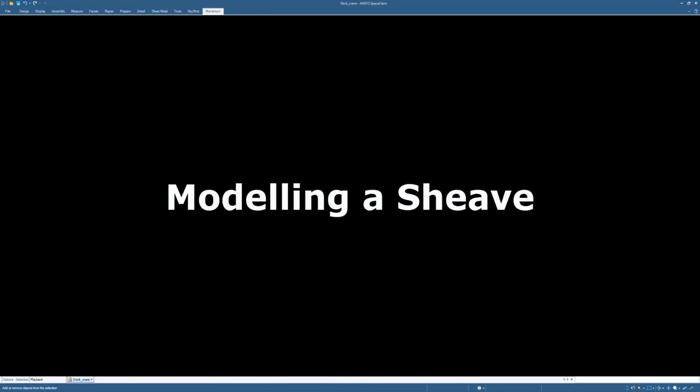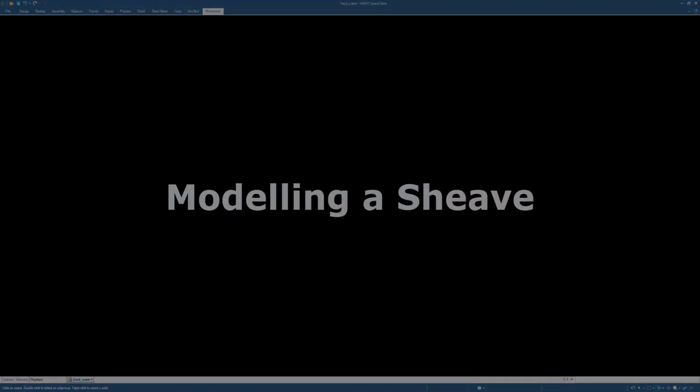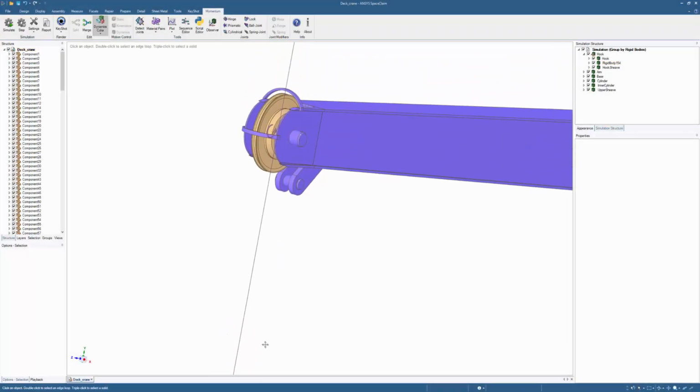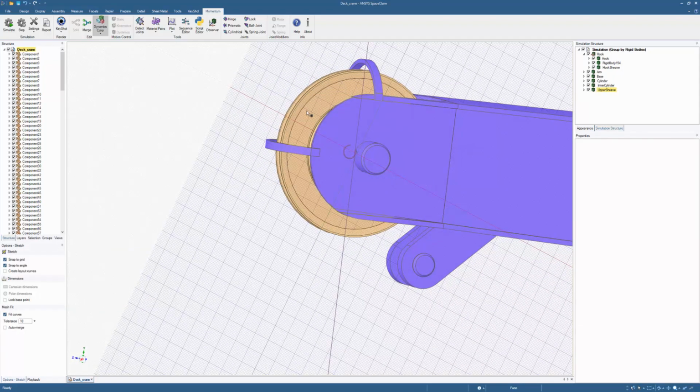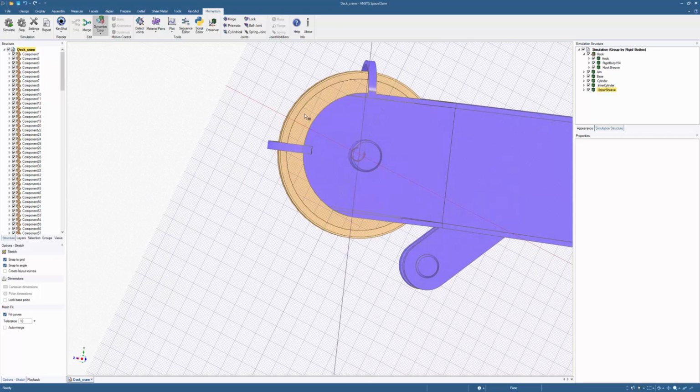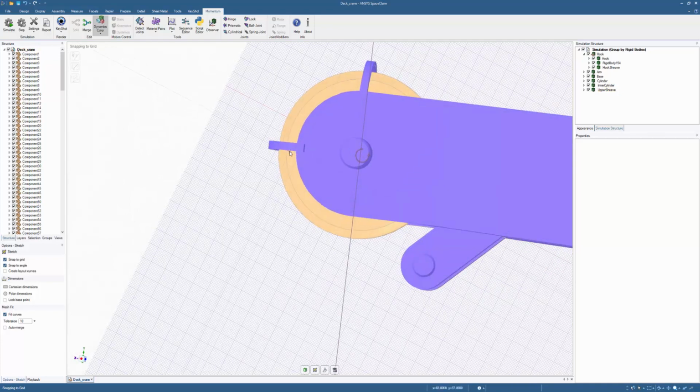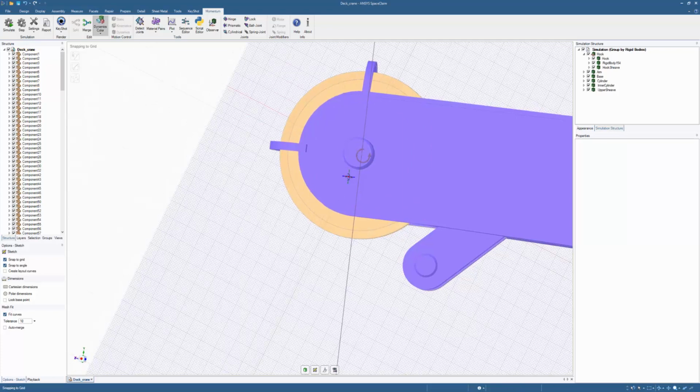To get a solid and robust simulation, we also need to model the sheaves as cylinder primitives. These are the primitives or the collision geometries that the wire will have continuous contact with. So we will route the wire over these cylinders. So we can design a new primitive by using the design tools available in SpaceClaim.